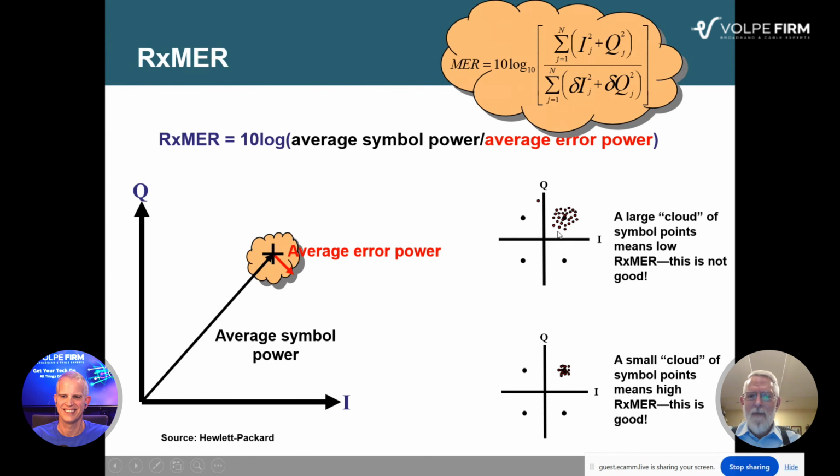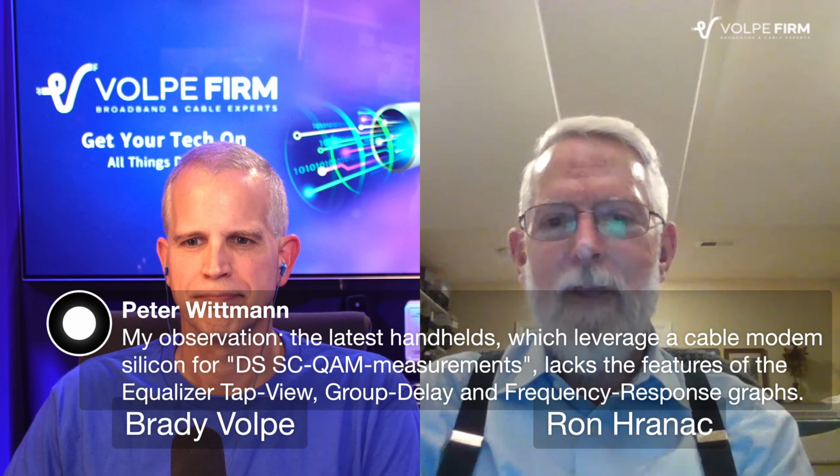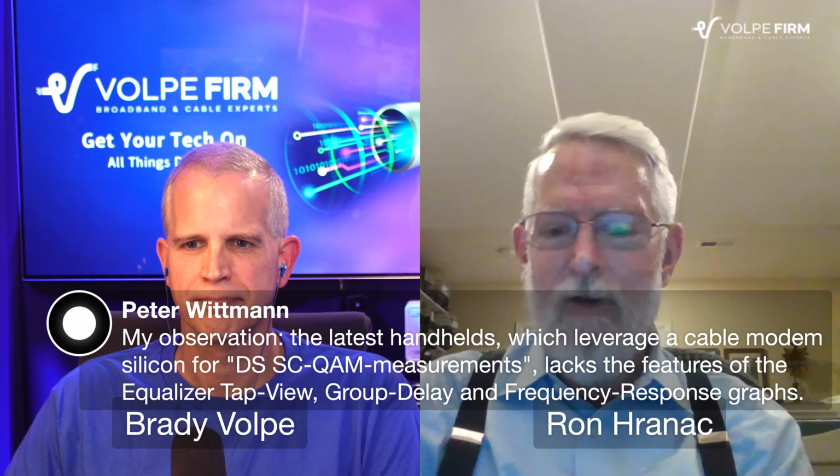This diagram I created. Actually, all these diagrams I created for that digital modulation slide deck that I did years ago, and I had some examples that showed that if you got this guy off here, you get a bit error. Whether it's correctable or uncorrectable depends on whether the FEC can fix that. Because if there's too many of them, it can't. That's the issue. And I've got a screenshot later from a real QAM analyzer that shows some of those that are spread out from the ideal point. That suggests that, hey, you got some FEC errors going on here.